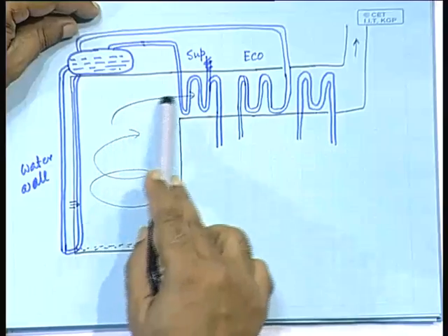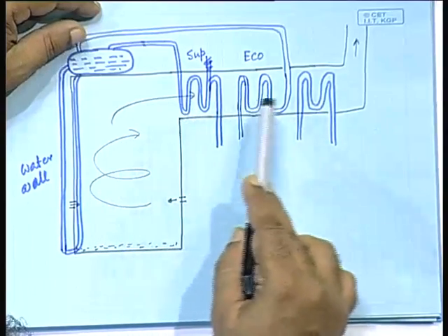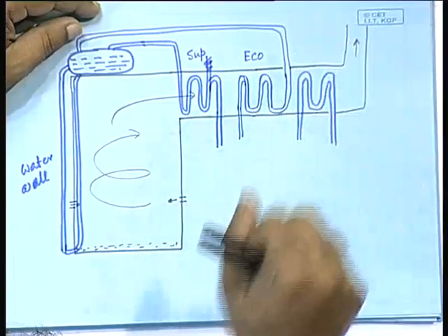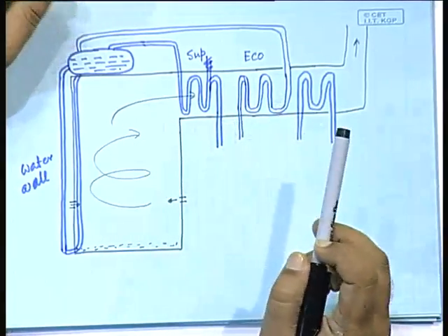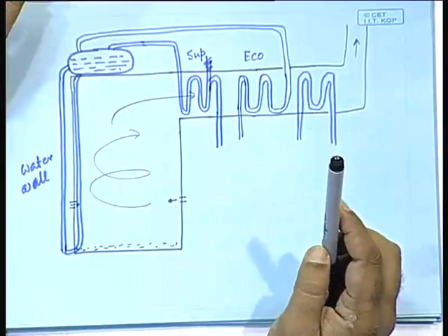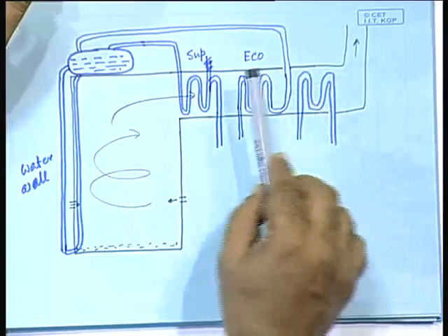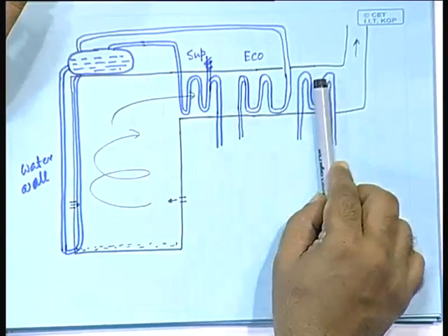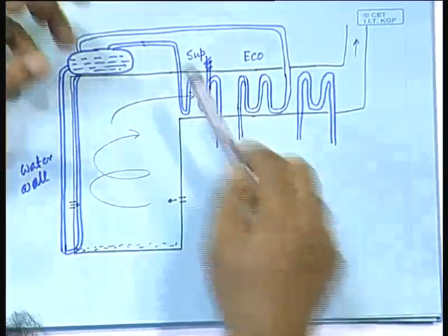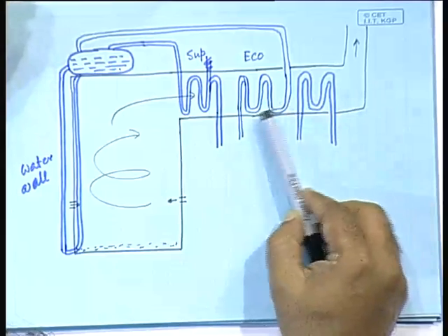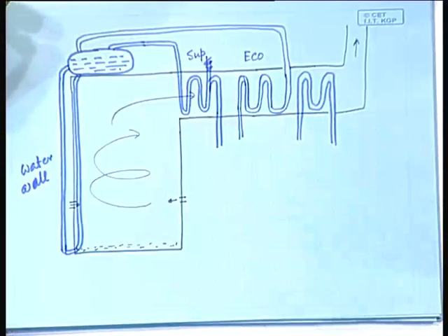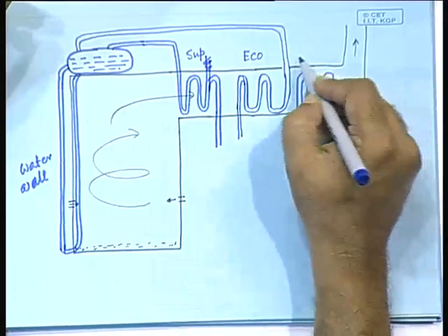While the flue gas goes out, there are three stages in which the heat is extracted from there. The first stage is the superheater. Normally the reheater stage comes after this and the economizer stage comes after that, but nevertheless, since we were exposing it in a particular way, we have drawn it as the economizer first and the reheater next. So, here it is.